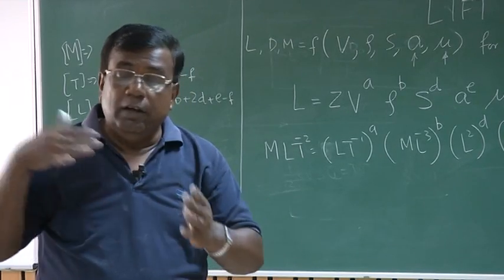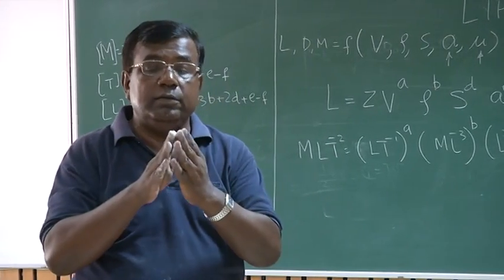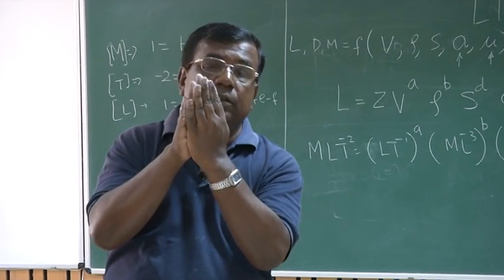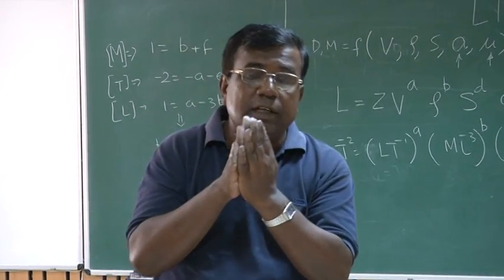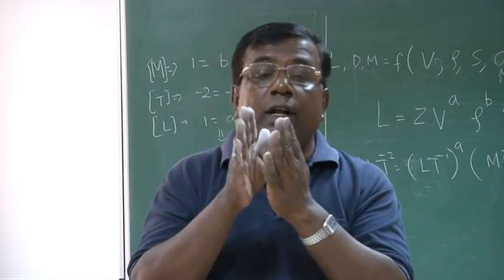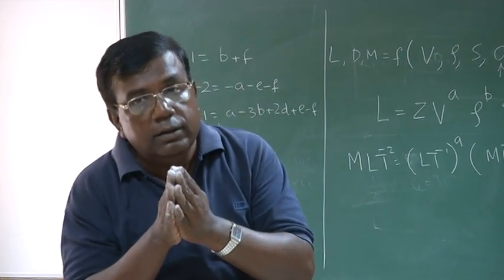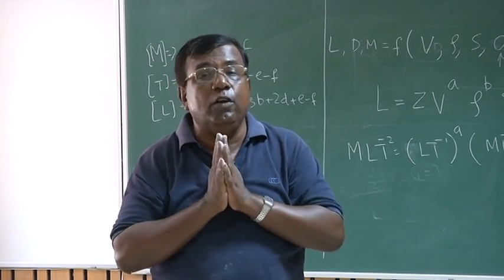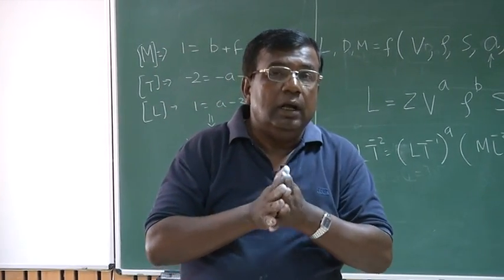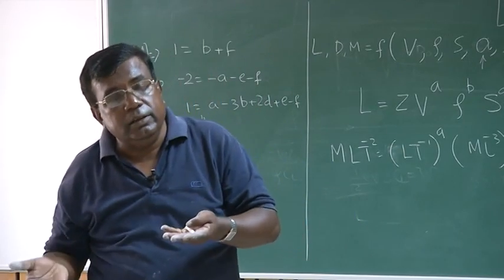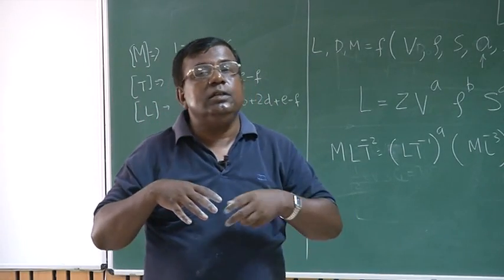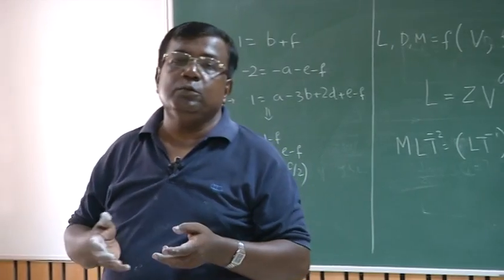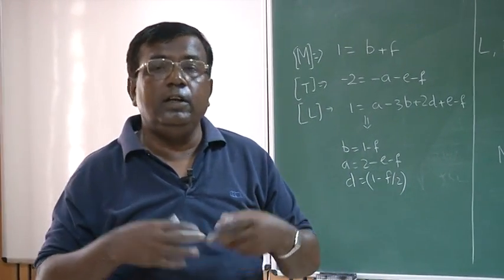So because now the velocity of the body is more than the velocity of sound, there will be a compression. Okay? And that compression means a lot of energy it has absorbed from the vehicle, and hence we say it will increase drag, or we say there will be formation of a shock wave. And the shock wave again will interact with the body, and it will again redistribute the pressure distribution.